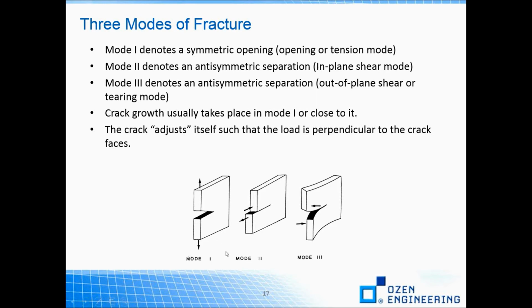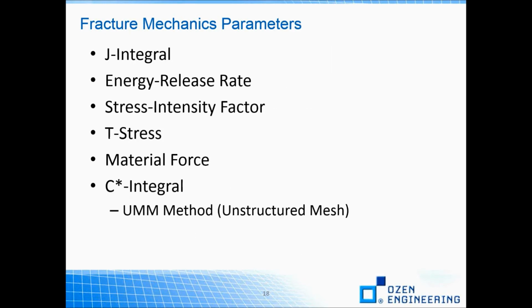In general, crack growth is a function of any of these modes or a combination of two or three modes. However, crack growth usually takes place in mode 1, or to put it differently, the crack basically adjusts itself such that the load is perpendicular to the crack faces.